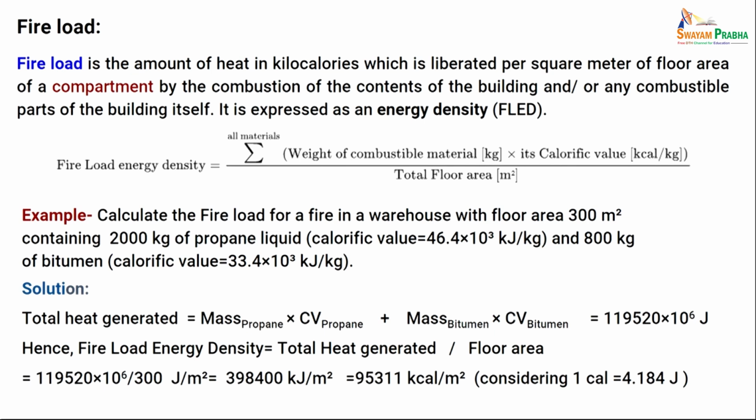So, fuel weight in kg times its calorific value divided by the total floor area, because the materials are within a space, will be considered as the fire load energy density. If you see here, fire load energy density is also called FLED. So, it is per unit area in meter square, because space is mostly measured in meter square.